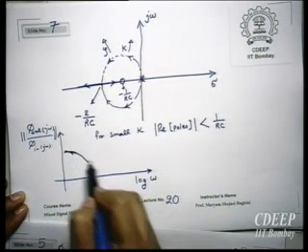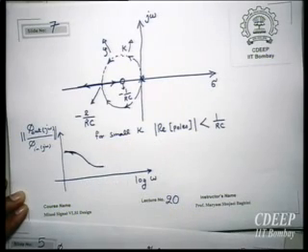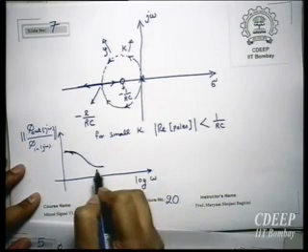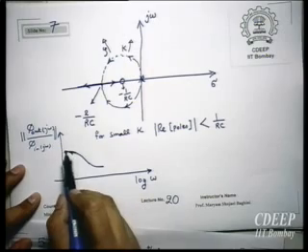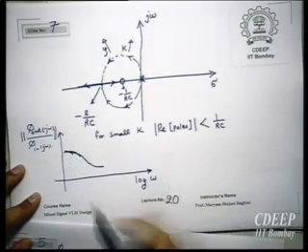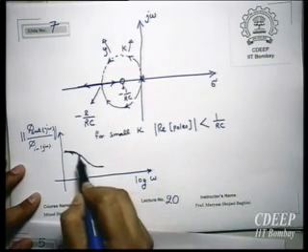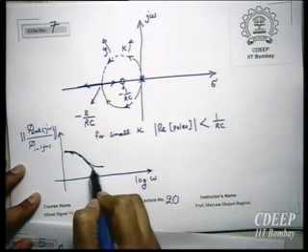And then it will be flat because of the 0. Not flat, actually; it won't be completely flat because this is second order. Therefore, effectively here, because this is second order, we have 2 poles and then we have 1 0. So effectively here we'll have more slope and then it will have less slope.